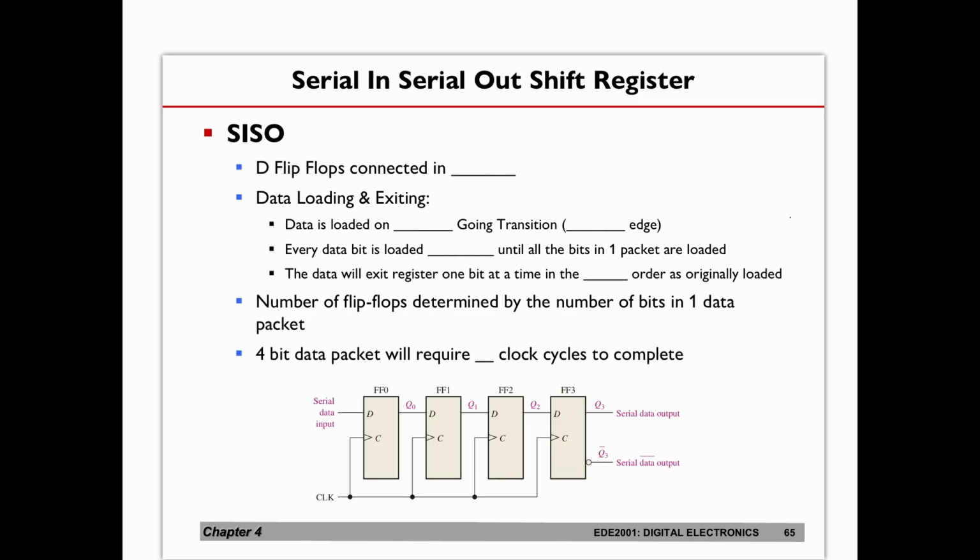Take note that whatever we have been talking about so far, shifting data or storing data, has been about 1 bit. If I have 4-bit data or maybe 8-bit data, then we will need shift registers to store the data. Then, when the data needs to be sent to the output, it can be sent out one by one, or all at once.